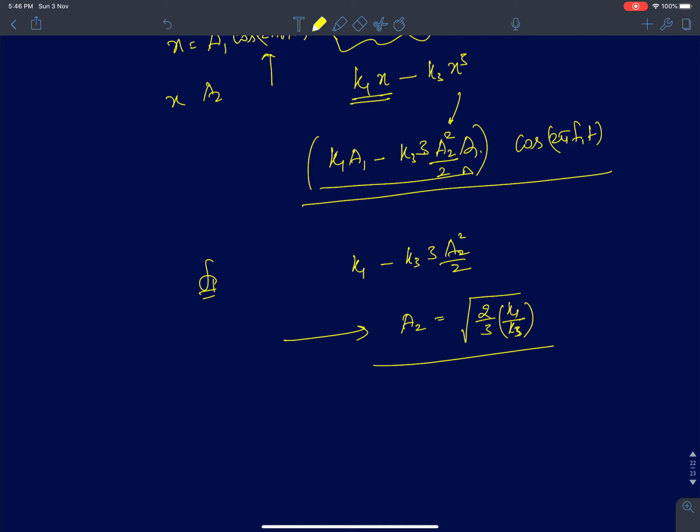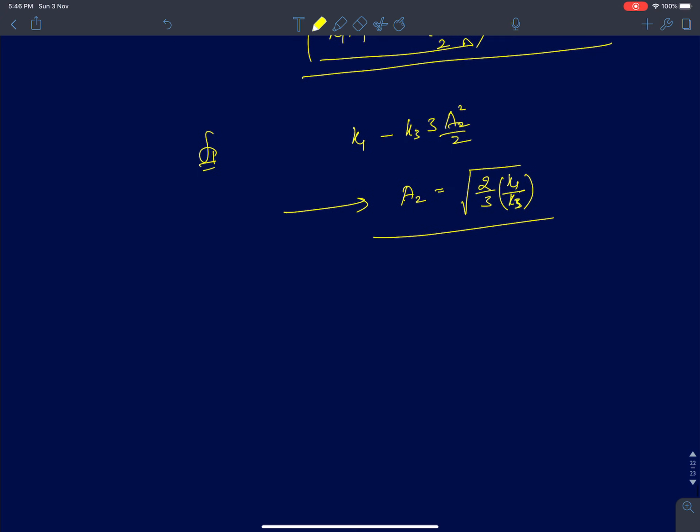Okay, so this is called blocking. I mean, the signal completely blocks it, or receiver desensitization. Okay, so I'm just throwing in a lot of words. So all these problems occur because of nonlinearity. So one is interferer, it interferes with your reception of your desired signal, or blocker, it can completely block your signal because of nonlinearity, and this happens because of gain saturation.